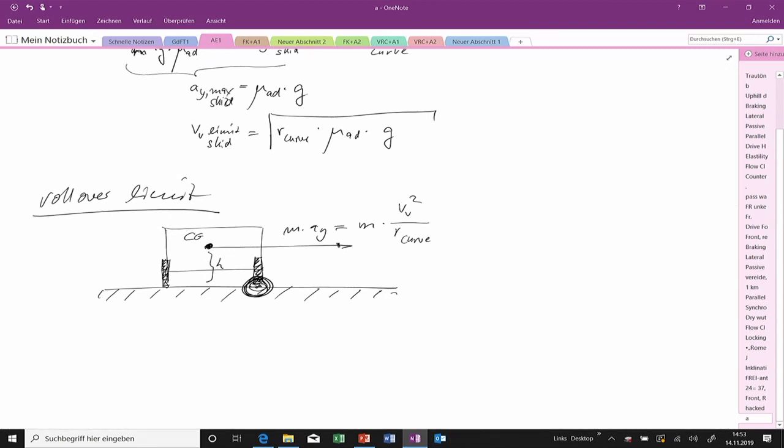And there is another torque which is working against that rollover, and let's assume that the distance between both wheels, left to right, is s, or no, it is called here s_t. Which means that if the center of gravity is in the middle of the car, which we could assume, then we will have here s_t divided by 2.